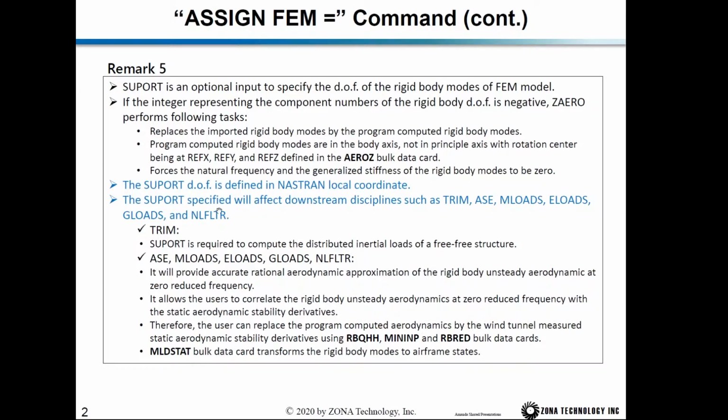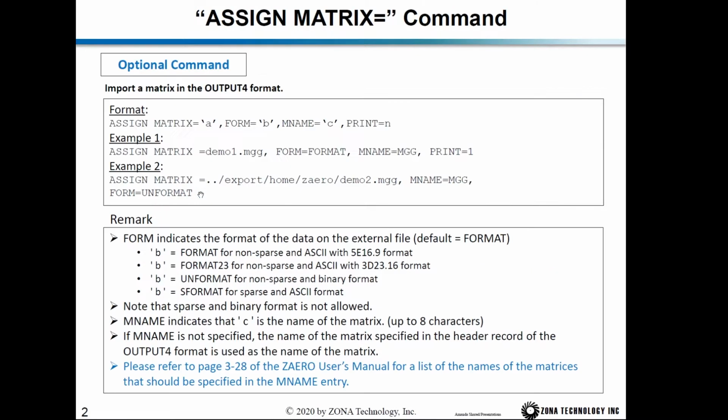There are many reasons, and it is always highly encouraged to specify SUPPORT equal to negative, followed by the degrees of freedom of the rigid body modes. We will talk about why we need that in later sections.